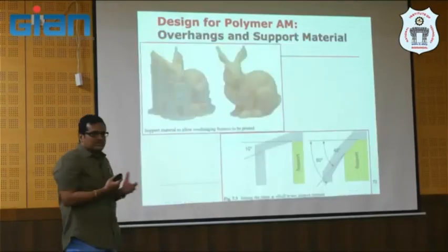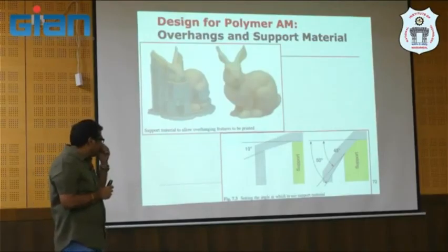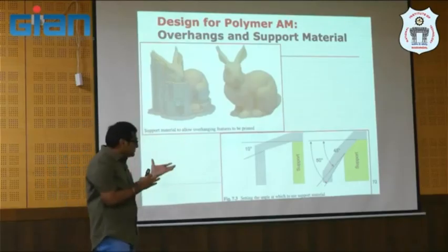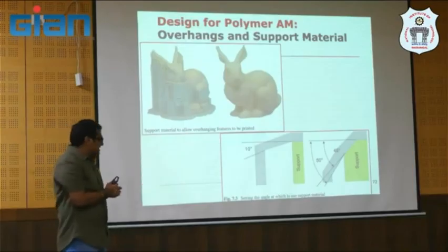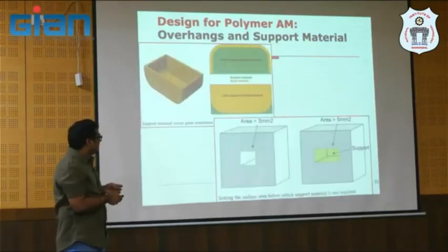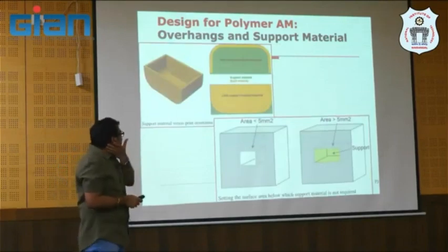So in the supports, yes, it's the biggest challenge. Supports, then you tackle with a kind of overhang angle, right? You have some thumb rule, 45-degree. You try to manipulate with those kinds of things, and then the area also makes a lot of difference here.